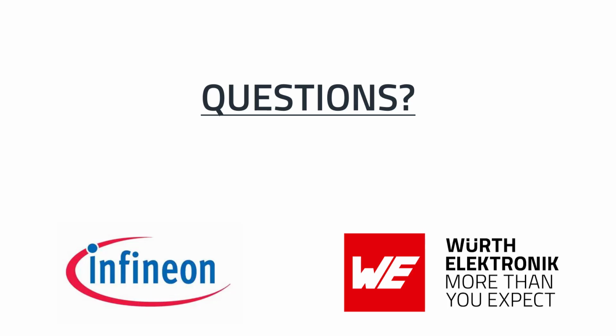Our next question here: how does interwinding capacitance affect CMTI? I think that I already have mentioned it when I was explaining in the webinar, but the interwinding capacitance is the parasitic between the primary and the secondary. So this becomes a very big deal when you are working with fast switching devices like silicon carbide or GaN. As for the ideal CMTI for these kinds of switches, let's say 100 kilovolts per microsecond or above, literally 150 also, would be okay. But again, it all depends on the switch that you're going to be using for your application.